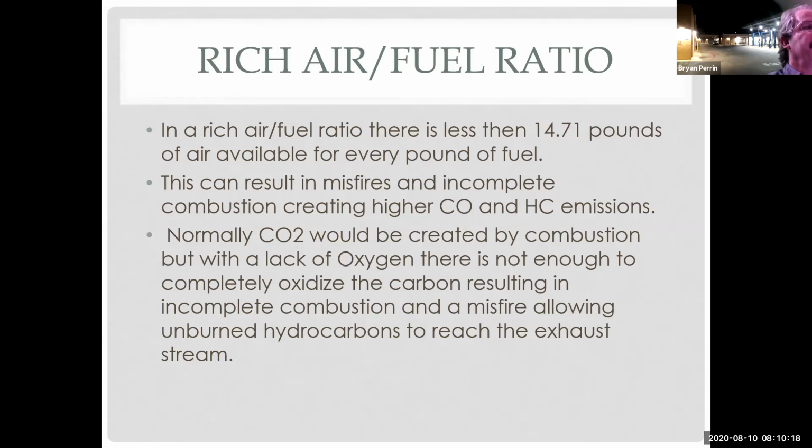So with a rich air fuel ratio, there is less than 14.71 pounds of air available for every pound of fuel. This can result in misfires and incomplete combustion, creating higher CO and HC levels. Normally, CO2 would be created by the combustion, but because of the lack of oxygen, there is not enough to completely oxidize the carbon, resulting in incomplete combustion and a misfire, allowing unburned hydrocarbons to reach the exhaust stream.